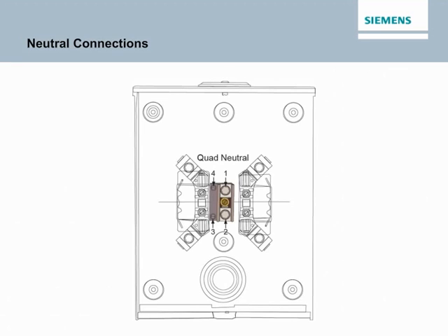All sockets include a neutral connection. The neutral conductor serves as a current return path. The neutral conductor is connected to ground at the service entrance. This is accomplished in a meter socket by connecting the service ground and neutral conductors to the same point in the meter socket enclosure. A bonding screw at this connection point secures the ground to the interior of the meter socket enclosure. Keep in mind that neutral conductors are not connected to ground at any point downstream from the service entrance.